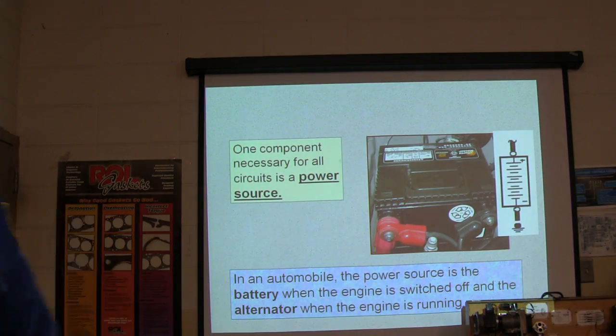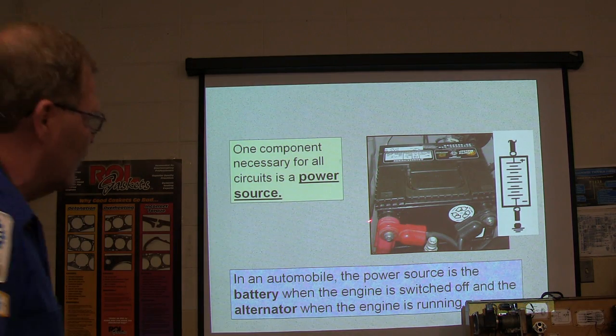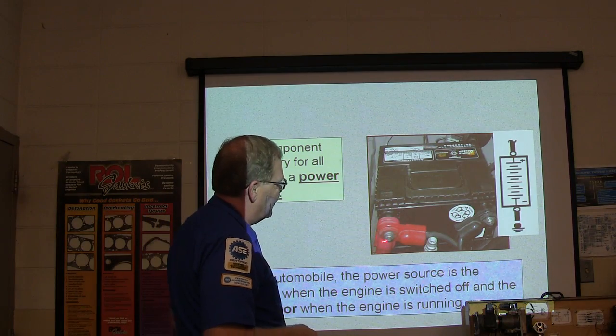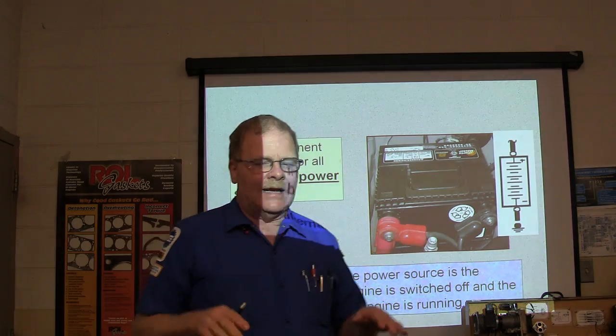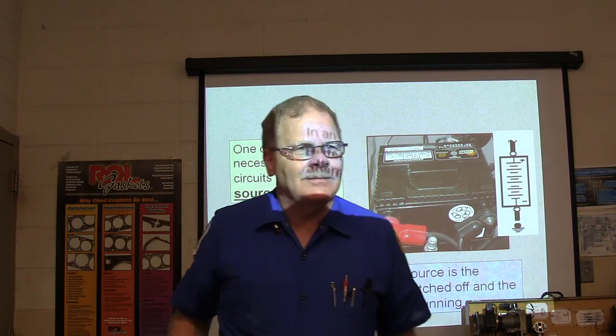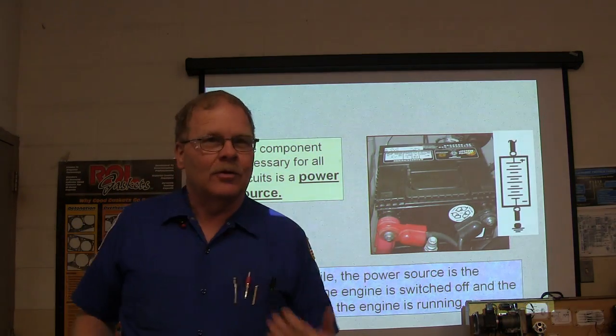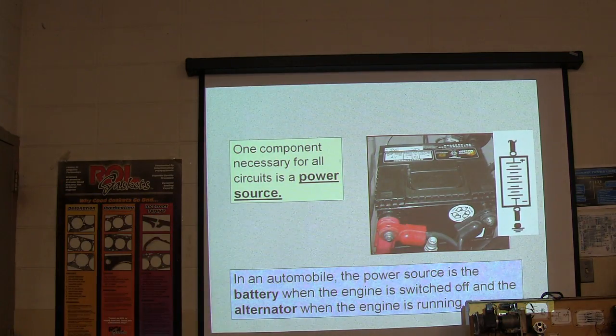So you gotta have a storage component. You got a battery that's coming out of the loop. In other words, for example, if you've got really, really dirty terminals right here, you can actually get a car that'll just quit running because of dirty battery terminals going down the road. You know?